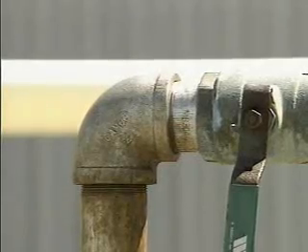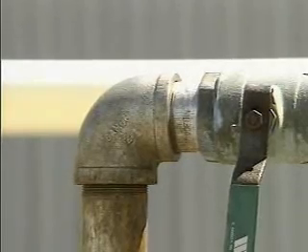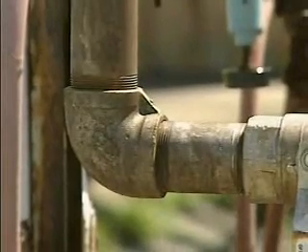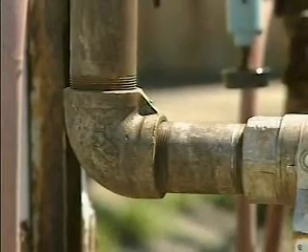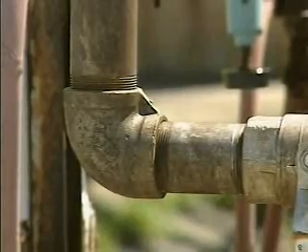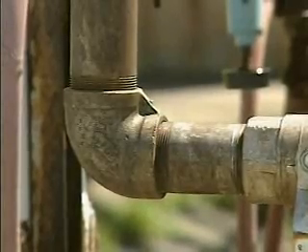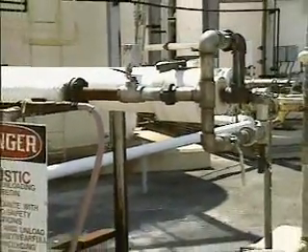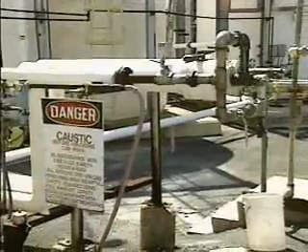Additionally, stainless steel can be easily sterilized by chemically treating the piping and then flushing it with water to remove the chemical residue. This prevents contamination and makes it a good choice for systems in pharmaceutical, dairy, and food processing plants. Stainless steel is also corrosion resistant, so it can be used to transport many corrosive liquids, such as acids and caustics.